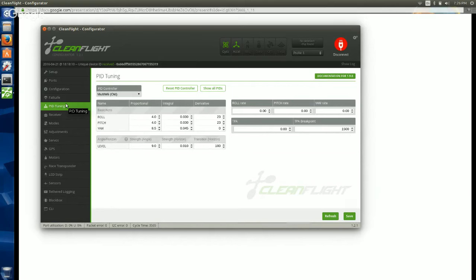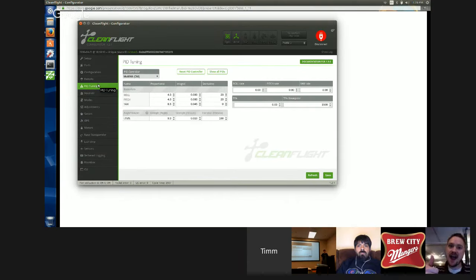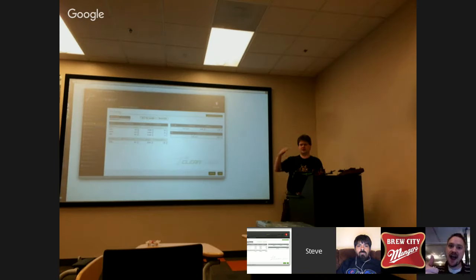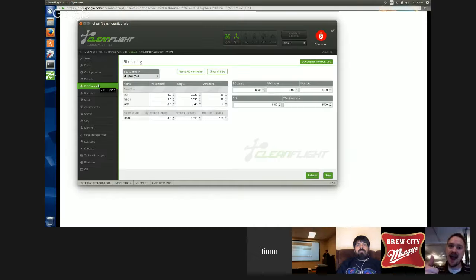And now you've burnt whatever you got in there. So next time you get a little bit smarter and you pulse the button until it gets up there, and then it just kind of waves around that 350 degrees real nicely. And that's what a PID controller does. It's 3 different numbers that you have to tune that tell it how to kind of pulse that button. And that's actually how the flight controller controls the motor speeds.